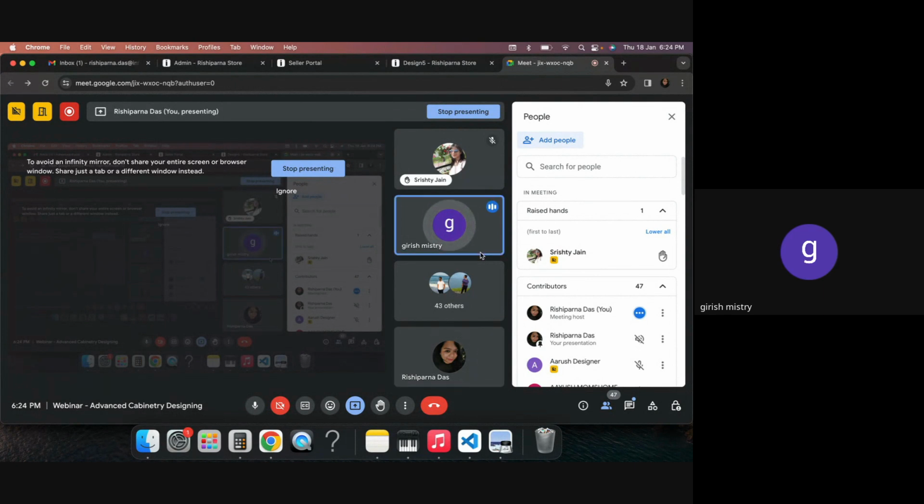One side 18 mm side is there. We want a through and through groove. How can we make this groove? To make this groove, you will have to put some cam details in a hardware, and in that hardware you configure at the back end exactly how much depth of drilling, and the radius of the drilling and all that. So if you put all that information inside the hardware, you can add it as a hardware.